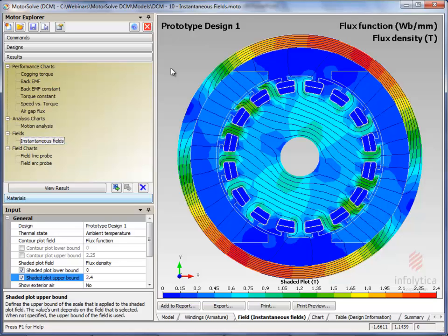This will be instructive when trying to assess thicknesses of permanent magnet, thicknesses of the surrounding core iron for the stator. It'll also be demonstrative and can help with the choice of the definition of the teeth for the armature, so that you can review whether or not you are saturating, and whether that's a derogatory thing or not, depending on the design criteria.